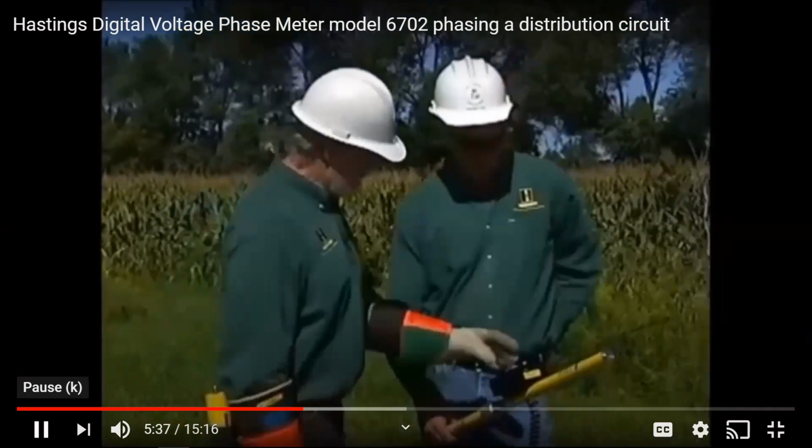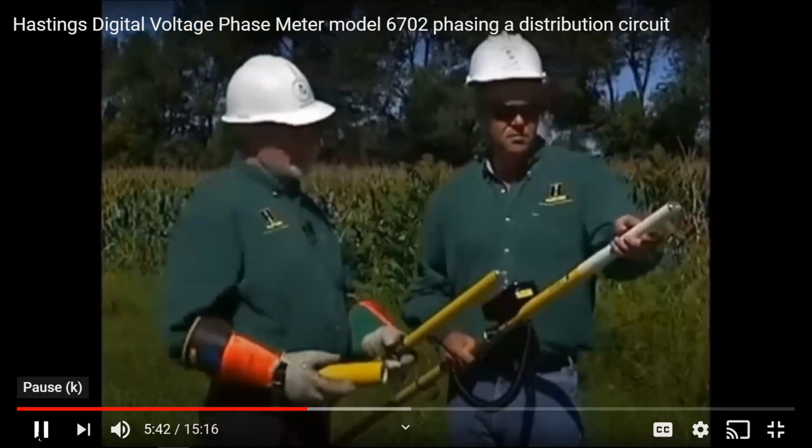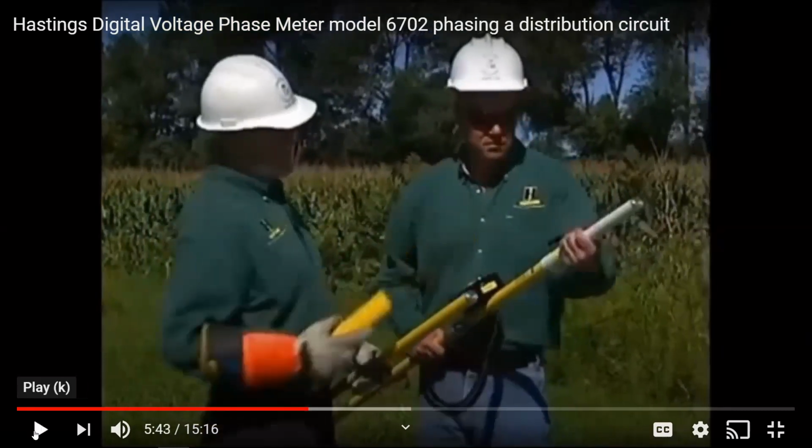Kirk, you've got your meter already set up on your hot stick, and I've got the non-metered end set up. Do you remember the previous safety video that you saw with Crepesi? All right, he's using the same meter and the same sticks. These are two phasing sticks that he's using right here. The right-hand guy has the digital meter side, and in that hand, that white section is what they call the high pot adapter.